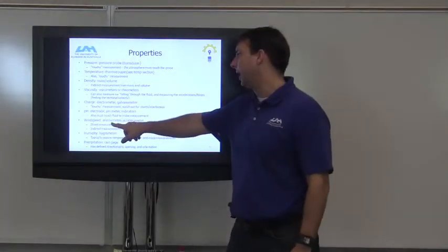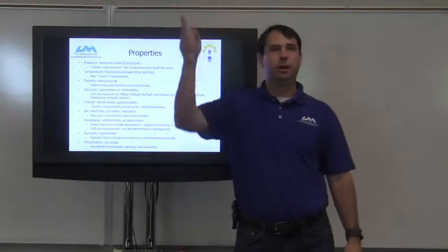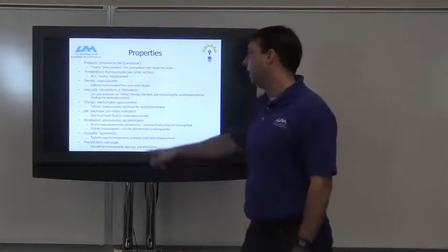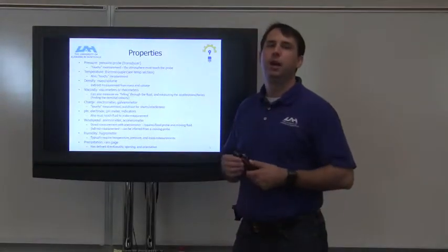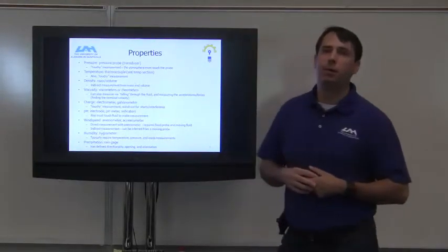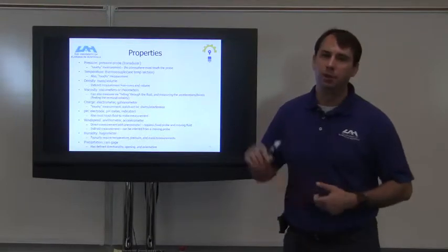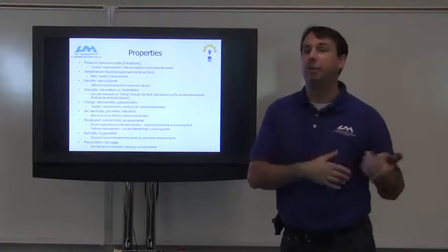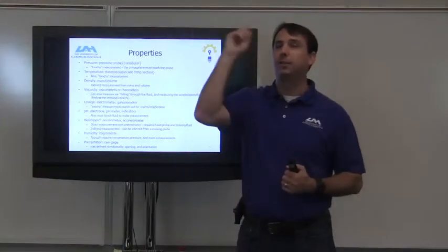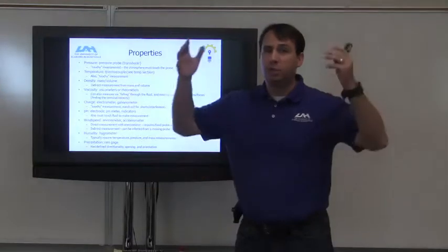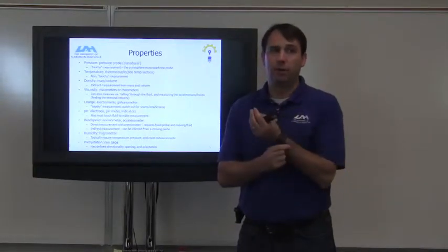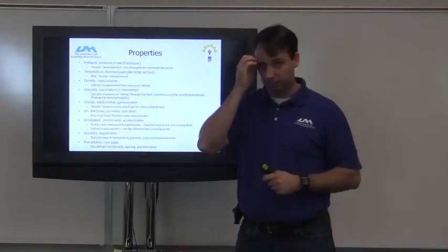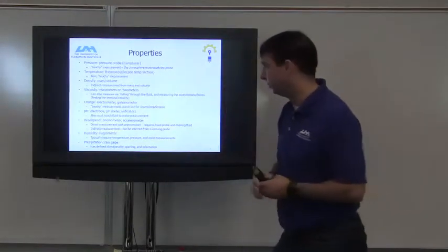Wind speed, you can use an anemometer. Those are the cups that are on top of the car, like the storm chaser vans. The cups that spin around, that's an anemometer. An accelerometer can also be used, or an IMU. An IMU is an inertial measurement unit. We'll talk about both those in a minute. But those can be used to calculate wind speed indirectly. An anemometer calculates it directly, but an anemometer requires something to be stationary, either the wind or the thing, because it's a motion thing.